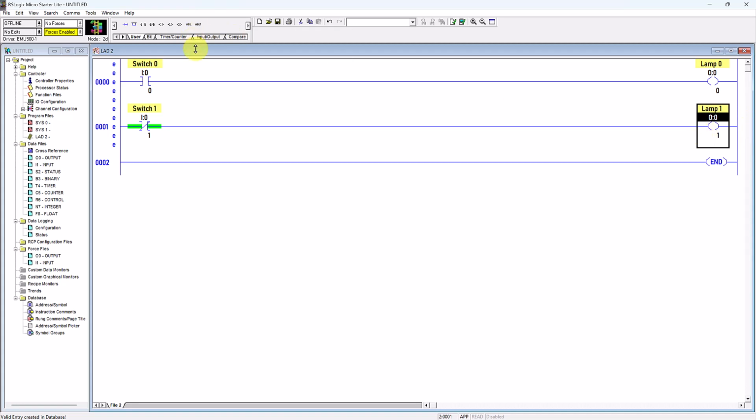Okay, so let me maybe create a new rung to explain so that it will be easier to understand. Instead of using this virtual output coil, which will waste our physical digital output terminal point also, in order to save the digital input terminal points as well as the digital output terminal points, we can use the memory.